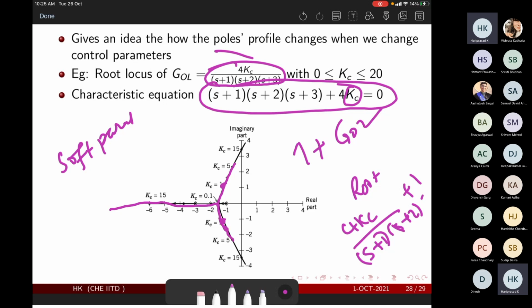After some critical value, let's say k is equal to 15 in this case, this root profile crosses the LHS, which is our green area, and goes into the RHS, which is the danger area. At this point things become overwhelmed and might go unstable.